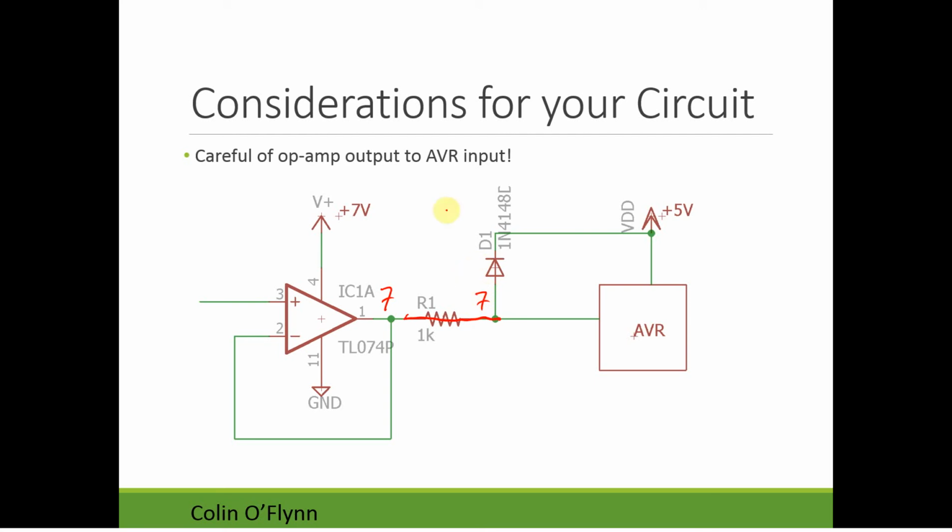At the other side of this, there'll be that 7 minus, what's that, 6.3-ish volts. If this 7 volt supply has more power, it'll actually pull up your entire AVR supply to 6.3 volts, which is beyond what the limits of where you should be using it. And that's because this could be a potentially very strong signal source.